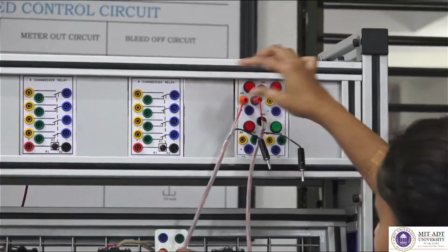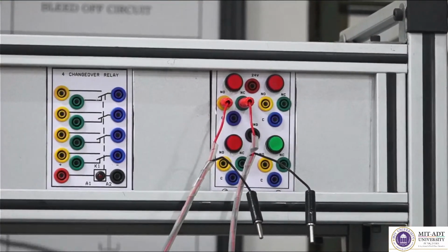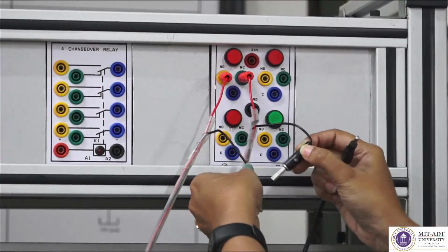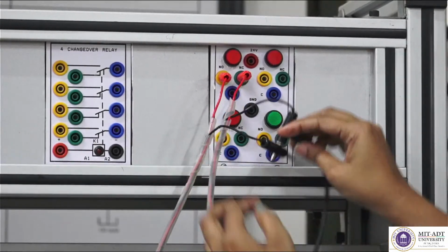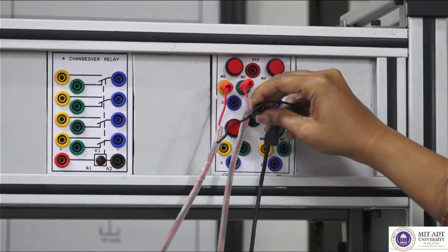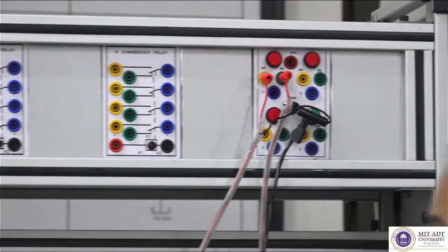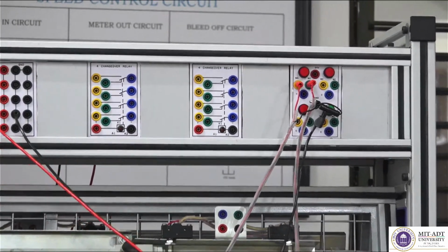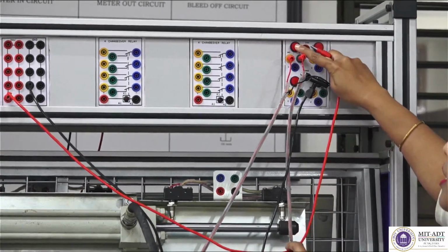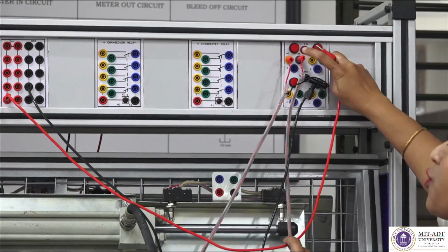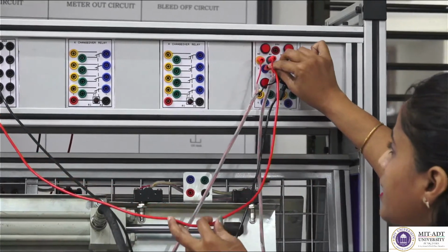Okay. Then both black wires would be grounded with the help of this black color wire. So I am grounding all black wires into one, and all wires would be grounded back over here. Still the circuit is not yet completed. Why? Because 24 volt supply is not given to a common. Common is shown with a blue color. Now you have made all the connections for this non-latchable push button, which is shown over here with a red color. So I am taking a 24 volt supply, I am giving it to this common.